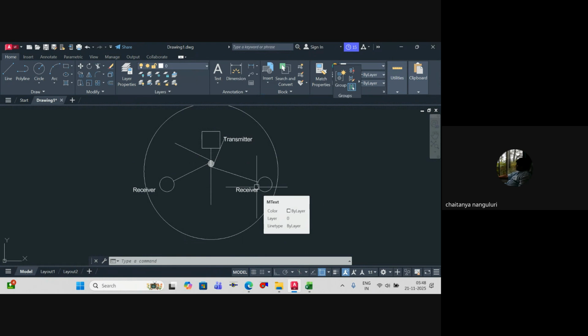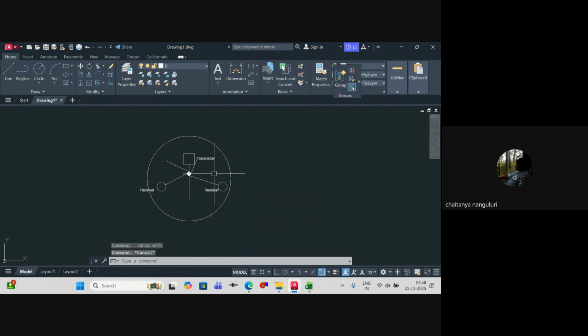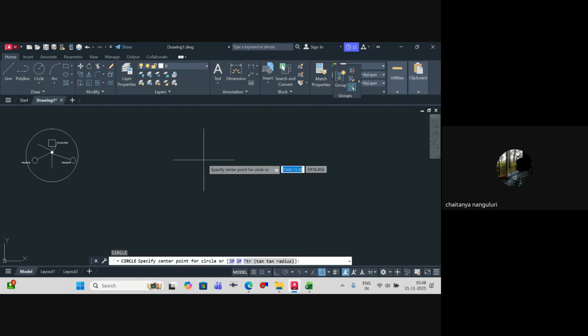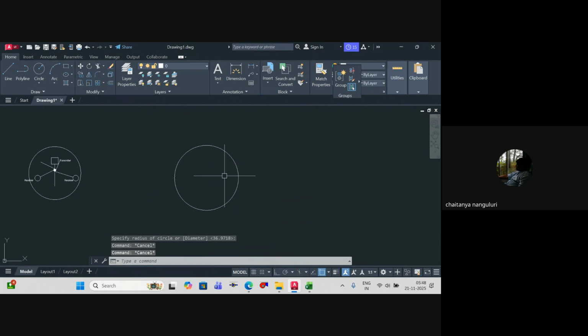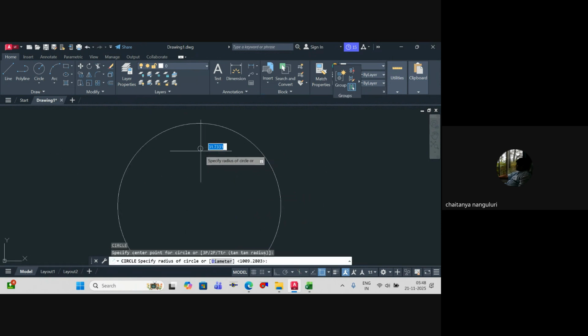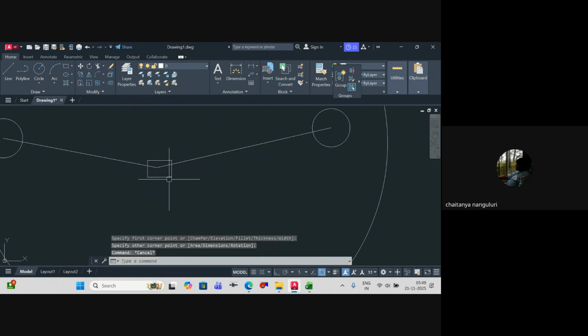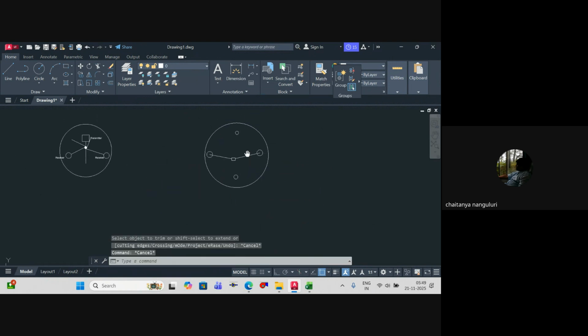Yes, sir. That is the spot type of detector. This is the simple spot type of detector, and the general wiring is simple. If you see the base of a detector, it will have four pins generally. Nowadays the wiring has slightly changed, but a few models still follow this. You have a small resistor between these two elements.